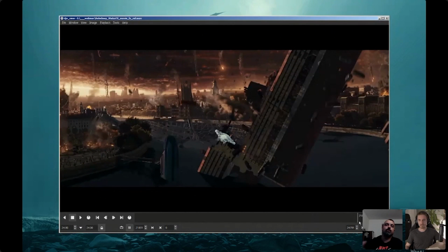Sometimes when you are learning the process, it's really good, and I will show one preview later, that you do the preview, the low-res sim, and try to create a shot as good as possible with low to mid-res. Then if it's not possible, try to go with high-res if it's needed, if you see the details of the mesh. But most of the time, the white water will cover any crazy splash. So, some students spend too much on the main fluid sim, but actually you don't need it.